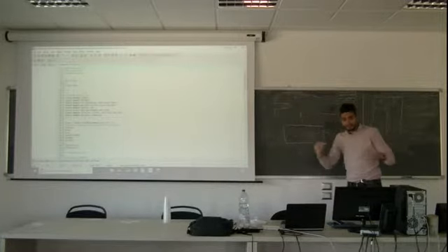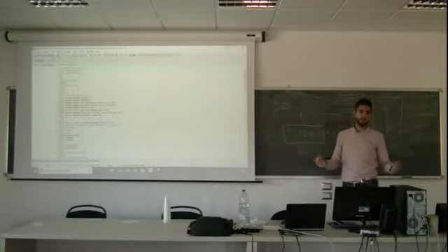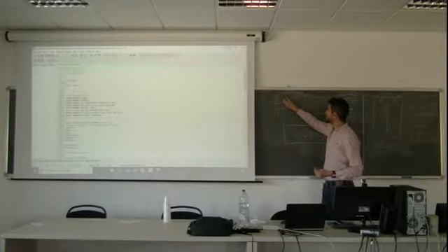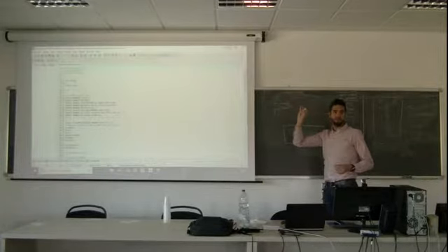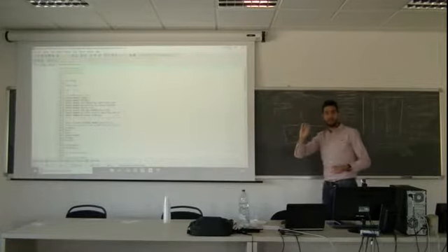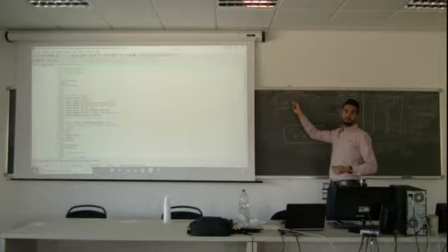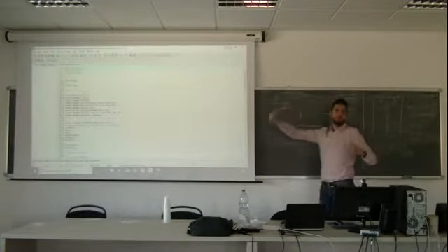Physically it is not fixed. It depends on the temperature of the air and the temperature of the node, and you have to compute physical properties of the air at film temperature. So for each iteration I need to calculate h. Do you follow me?